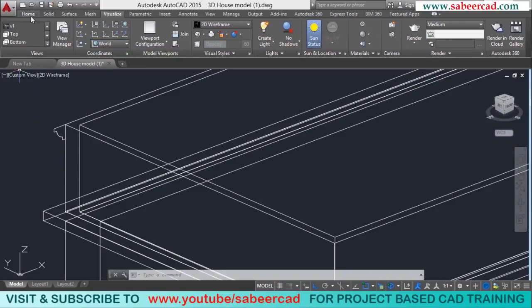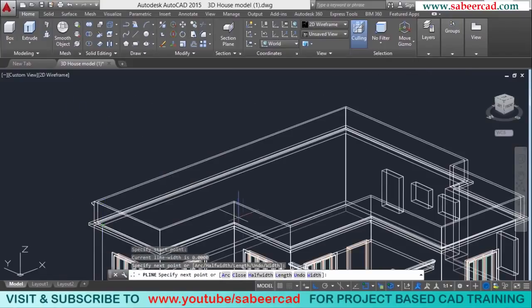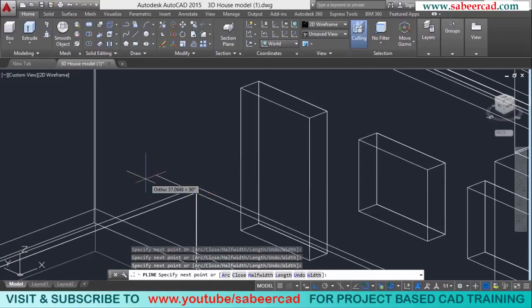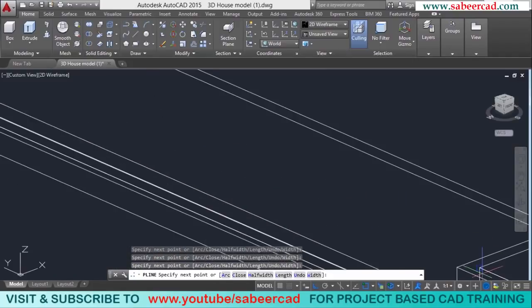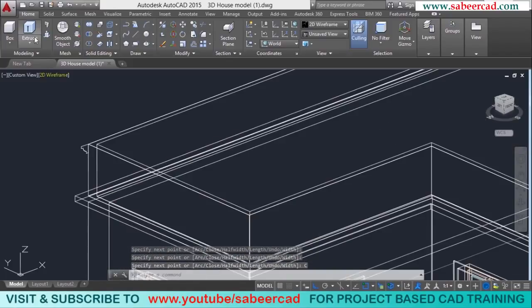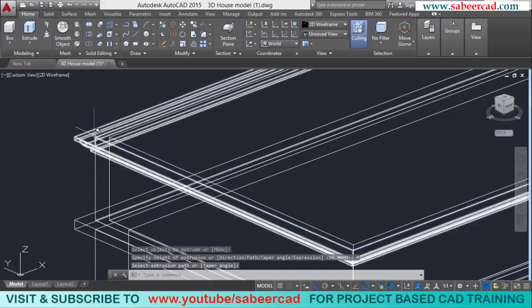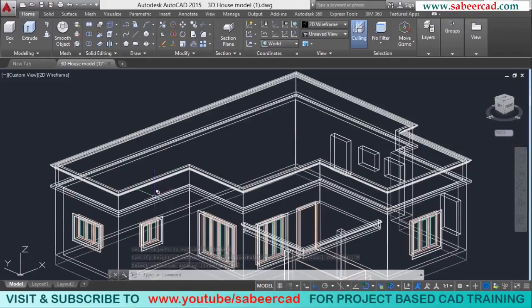Now I'll go to polyline again and I'll choose this as the start point. This is the end point. This is the next point, and I'll pick all the necessary points here. And I'll just give a close to complete the polyline path. Next, I'll go to extrude and I'll extrude this profile. Now I'll go to path option and I'll select this polyline path along which it is to be extruded. Now we have created a beading work which is on the top of the parapet wall.